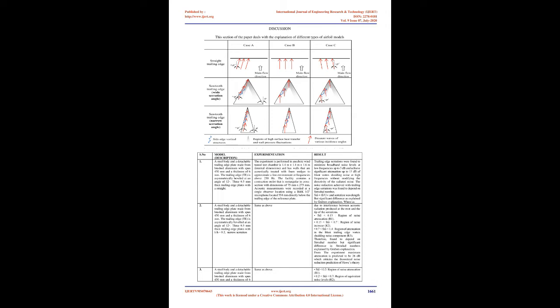However, Howe's theoretical model overpredicted noise reduction levels in the high frequency range while underpredicting the noise suppression in the low frequency range. Near-field turbulence measurements show that a serrated trailing edge could reduce turbulence strength in some directions and at some positions, and could also increase turbulence strength in other directions and at other positions. This result indicates that the noise reduction mechanism with the serrated trailing edge is very complicated.